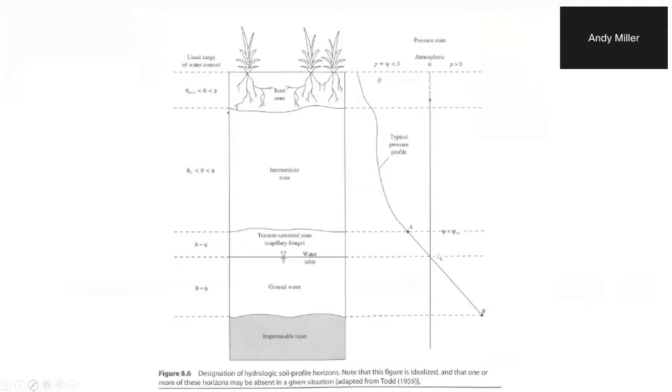So right at this location, Dingman makes the point that you have a tension head equal to what he calls the air entry tension. That will vary by soil, but essentially it's just the moisture that gets pulled up, very much like wicking into a narrow capillary tube, and the size of the tube affects that. But the main point here is that this is on the negative side.